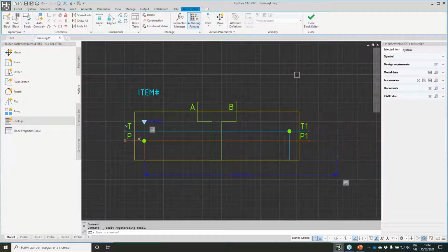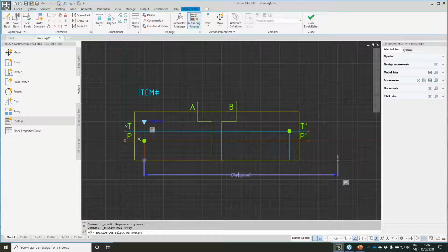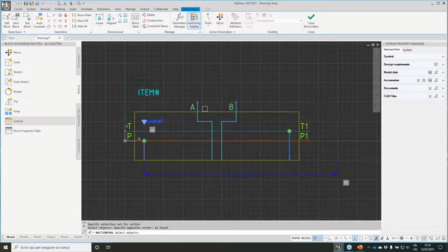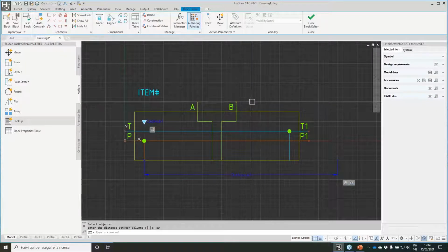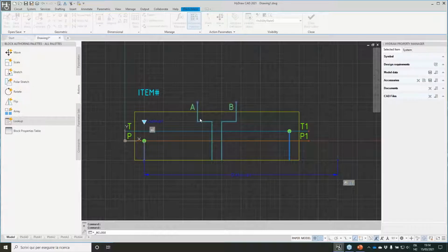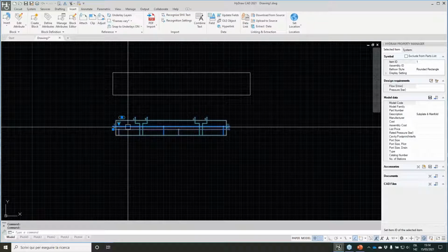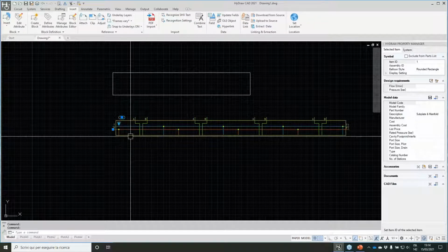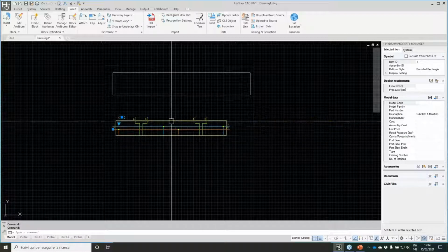And now I want to apply a new action, which is called array. The array is always selecting the same parameter, the distance one, and is applied to these entities. So the segment from P and A and B, enter, and the distance is 80 millimeter. Let's see, as you see down here, we have a new action, and let's see what happens now. Save changes. And now when we select the two station or three station, now our system is starting looking very good, because this is exactly what I want. I want to be able from a symbol to change between 2, 3, and so on.